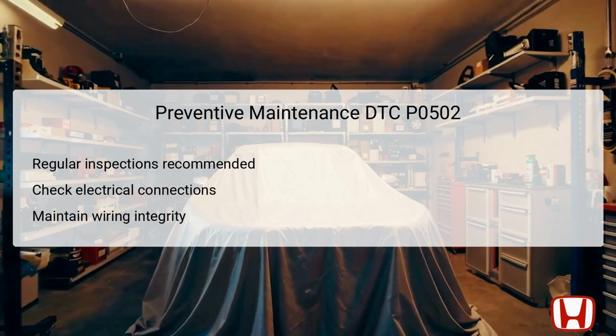Preventive maintenance plays a crucial role in avoiding future occurrences of DTC P0502. Regular inspections of the CVT system, particularly the sensor and wiring connections, can help identify potential problems before they escalate.